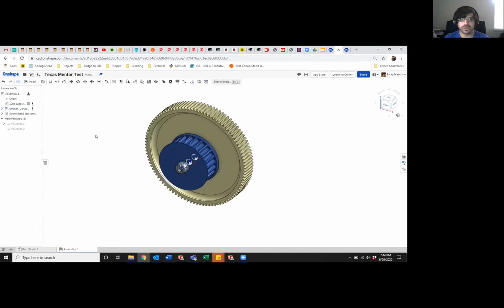Yeah. And then you can go back through the standard content tool. There's also this replicate feature that you can do similar things with. Yeah. Well, the thing I thought was more cool about the standard content is that if you click the face, it's got those holes. It tries to figure out what size to put in there. It plops them in every single hole. You can go back and edit it and say, well, I want a washer underneath, or I want a nut on the end. And it just builds that stack up for you without you having to constrain all the little pieces.